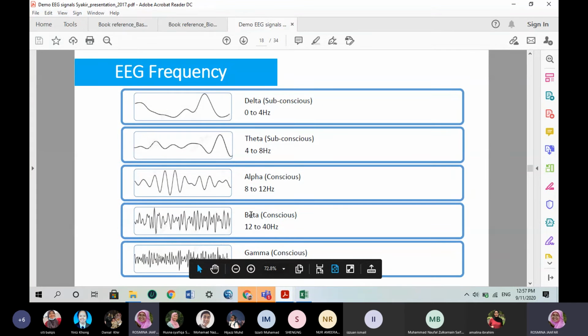But mostly during wakefulness, we have beta waves, because when we start thinking and we switch our mind from one area to another, processing, we have a lot of beta wave. If you are very relaxed, you listen to music, you become calm, your brainwave can change its frequency to an alpha rhythm, and so on. This is the basics of EEG signals in terms of frequency interpretation.